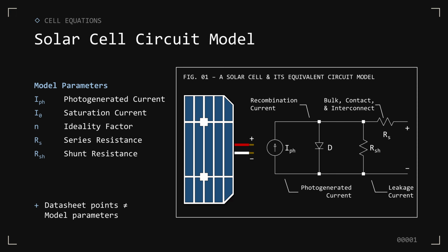Welcome to part 1 of a multi-part video series on solar cell modeling. The goal is to turn a solar cell's datasheet into a working circuit model, and end with a block you can drop into any LTspice sim. The first video is an introduction to the model we'll focus on, the single-diode equivalent circuit, which represents the solar